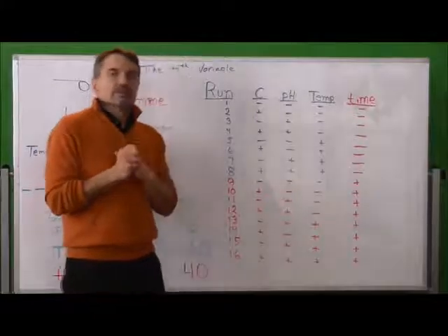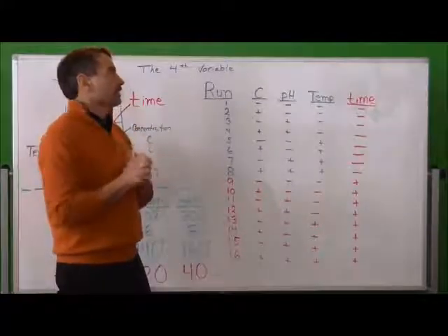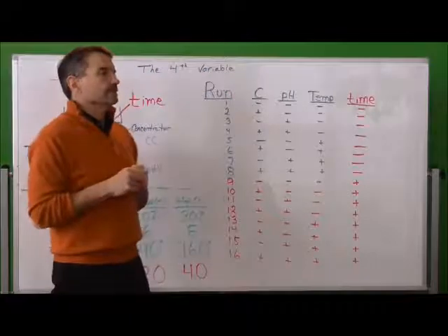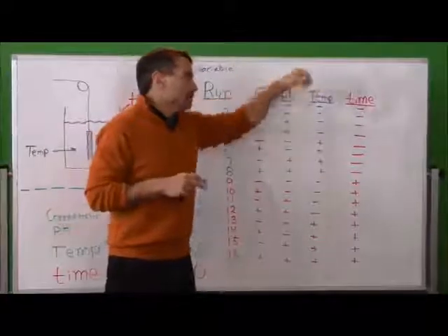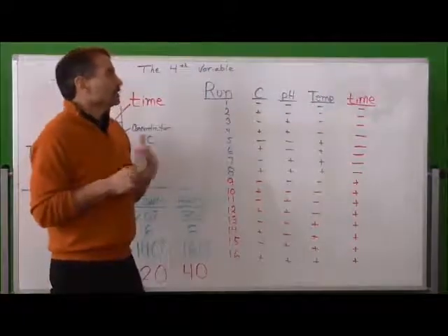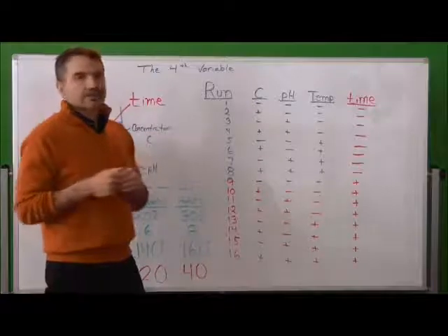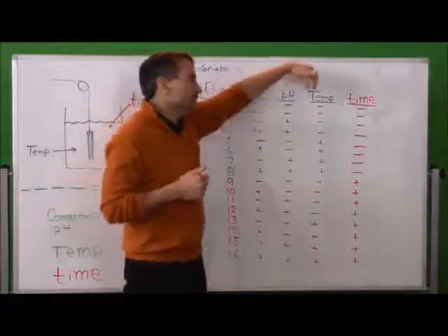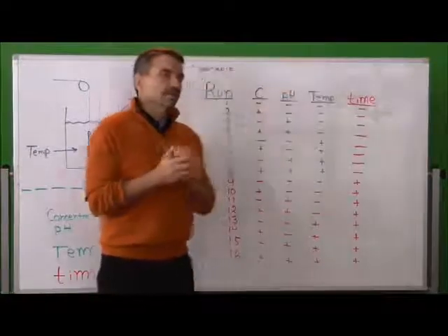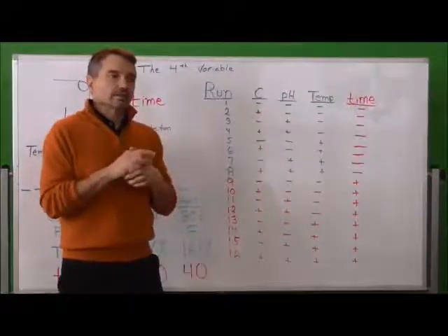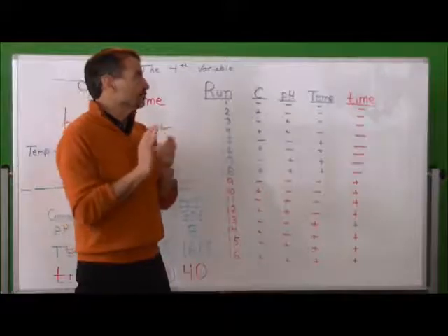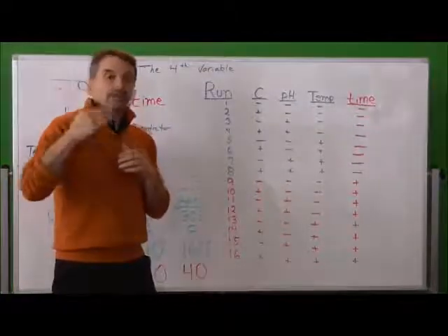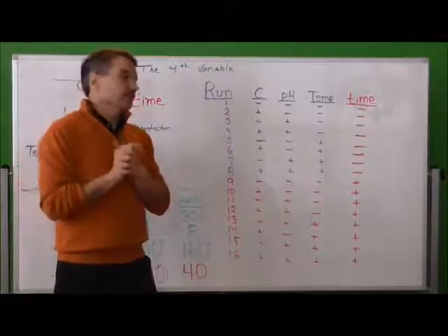We can also understand any of the potential main effects, such as the concentration by itself, or the temperature by itself. We can also understand the 3-way interactions, and the 3-way interactions might be the pH, the temperature, and the time, all acting in agreement with one another, such that when we have them all at one particular level, that's when we're able to eliminate the defect.